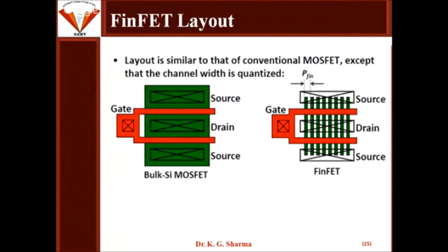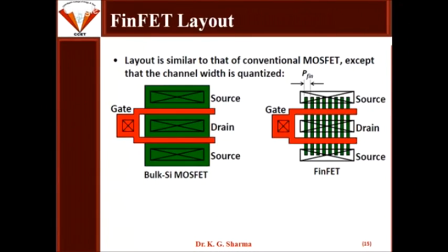If we talk about the layout, it may appear that we are switching from MOSFET design to FinFET layout design. We are very much comfortable with the MOSFET layout, so we always think that if we have to change to another type of structure, then obviously the layout becomes very tough. But no, it is not that. Layout is almost similar to that of conventional MOSFET. You can see from the figure the layout of bulk silicon MOSFET and FinFET. The layouts are almost the same, except that the channel width is now quantized. It is not all the same throughout, it is quantized.